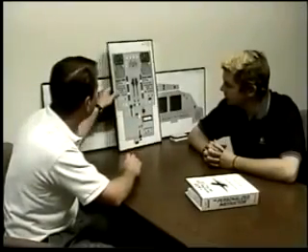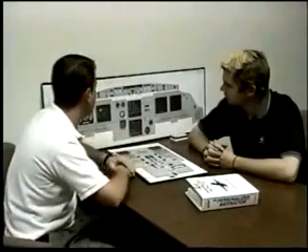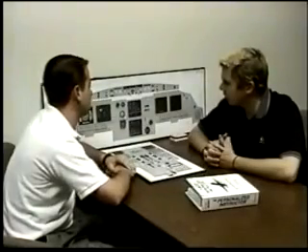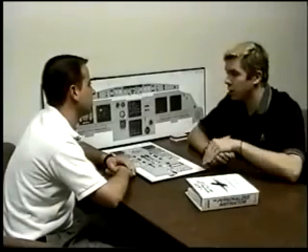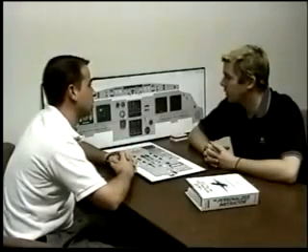You take off with flaps position 1 plus F. After rotation, you notice that you have an alpha lock indication below the flap number. What is that alpha lock indicating? Alpha lock, which truly indicates a slat lock, means that I cannot retract the slat from position 1 to up. I can retract it from any other position up to position 1, but I cannot go any less than position 1. What creates that alpha lock? Either being in a high AOA situation or low airspeed.